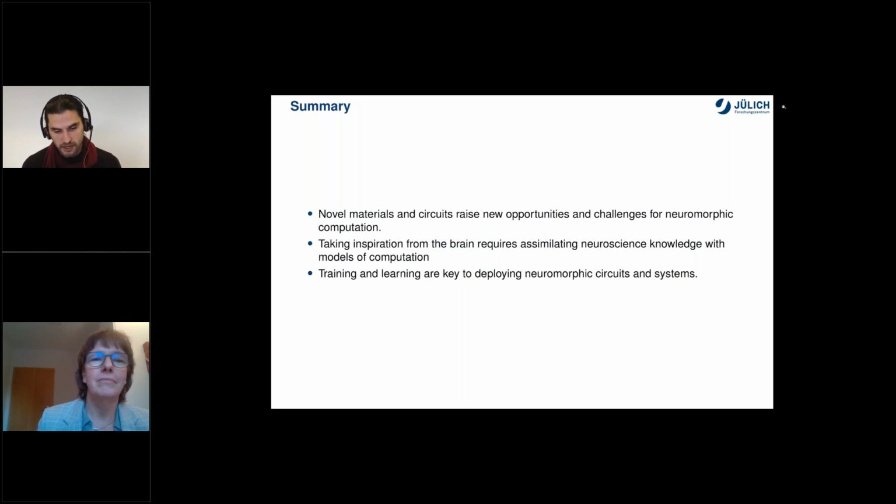The time constants of STDP need to correspond to the time constants of the neuron, which can be tens or hundreds of milliseconds. And so making those pulses hundreds of milliseconds may not be the best approach. Plus, and we see this both in our theories of the surrogate gradients and also in e-prop from the Wolfgang Maass group, it turns out that you require a trace that is specific to each synapse and not each neuron. And so this precludes the idea of using the presynaptic and the postsynaptic pulses as the carriers of the trace.